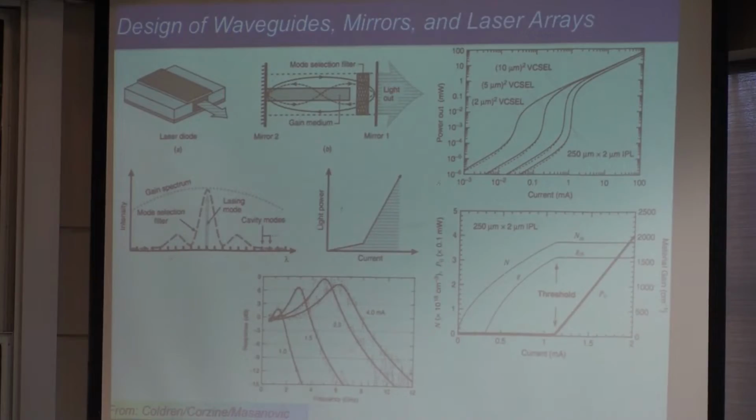So that's the idea. And then you get a single mode lasing with a semiconductor laser, and then the output power versus current would look like that. Here's experimental data, output power versus injection current. You are generating one in your lab one as well. There are a couple of other things that happen here. You have spontaneous emission. If you take this and plot it on a log scale, that's how it looks. Logarithmically, you still have output power at very low currents below threshold, but that's spontaneous emission. That's not coherent light. It's LED sort of behavior.